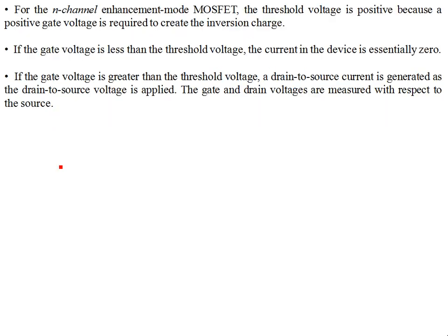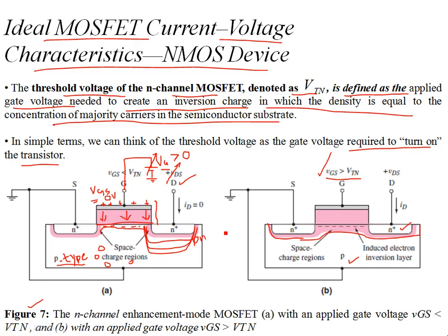So okay, for this n-channel enhancement mode MOSFET, I think I explained this earlier. If you go and watch the earlier videos, you see this in part 2 of MOSFET. Enhancement mode means that you need to apply a biasing to create the channel. If it is a depletion mode, then the channel is fabricated. It's already fabricated. It already exists. So you can even connect your gate terminal with the source terminal, and both can be grounded.